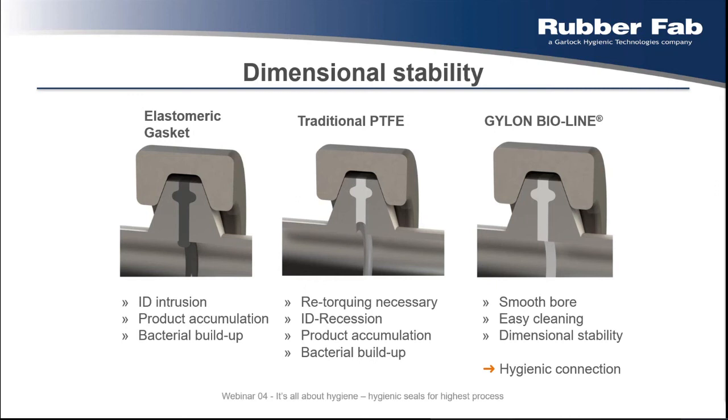They are rolled, then folded and rolled again, and this step is repeated many times, which results in a cross-linking of the PTFE molecules, giving the material an incredibly higher dimensional stability. It also improves the homogeneity of the material. For example, if you insert fillers, they would be distributed more evenly throughout the material.